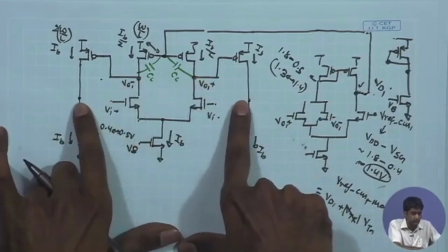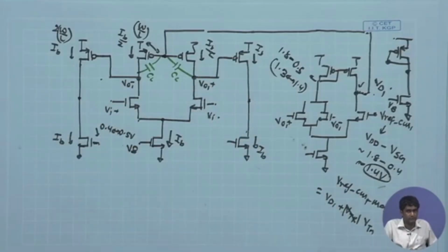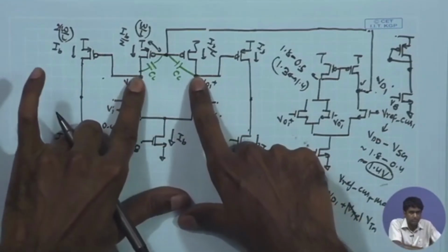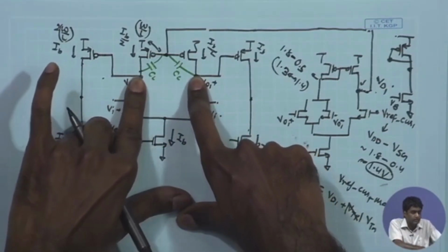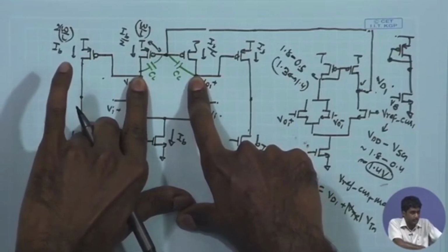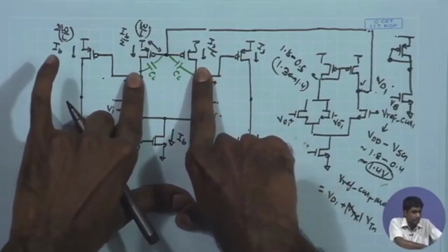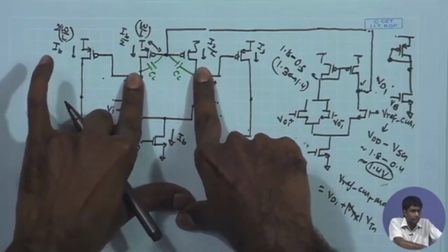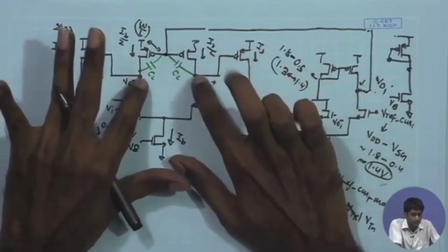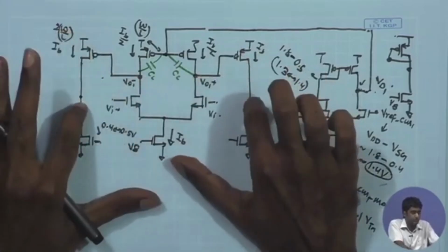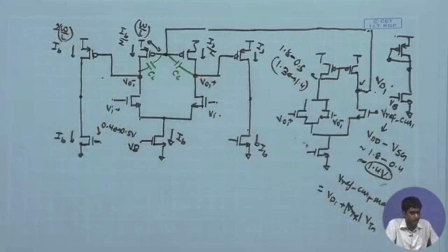As compared to this, the swing here is much larger, especially if you are talking about the first stage, a few tens of microvolts of signal. Here you may get a few millivolts of signal, and therefore it is not going to be so critical with respect to swing. Even 100 millivolt of swing available over here is good enough, 50 millivolt is good enough, much more than required. So, I do not worry so much about swing here, but yes, swing will be more of a concern here, especially if you are having a second stage of the front end amplifier with programmable gain.